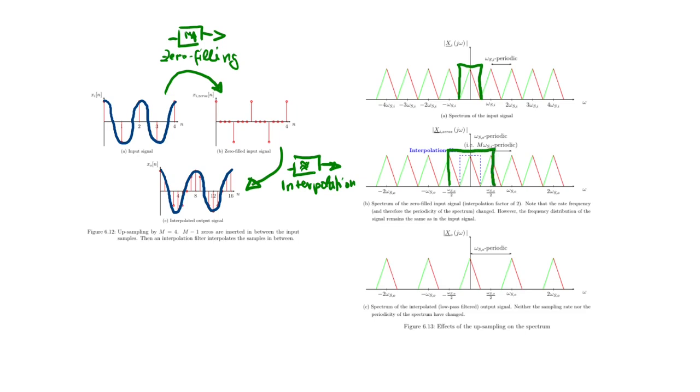So you see that actually our input spectrum is doubled within one repetition window. Here we use an interpolation factor of 2, m equals 2 in this example. So it's double here, but it's redundant information, and we want to get rid of this redundant information here.